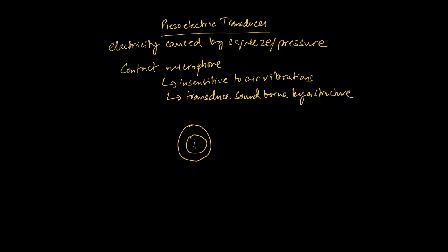The center is going to be positively charged. The outer side is going to be negatively charged. So when you apply pressure to it, if you hook it up to some kind of a voltmeter, you might actually get a signal. If the disc is cracked or scorched, this thing is not going to function at full sensitivity. So just be aware of that.